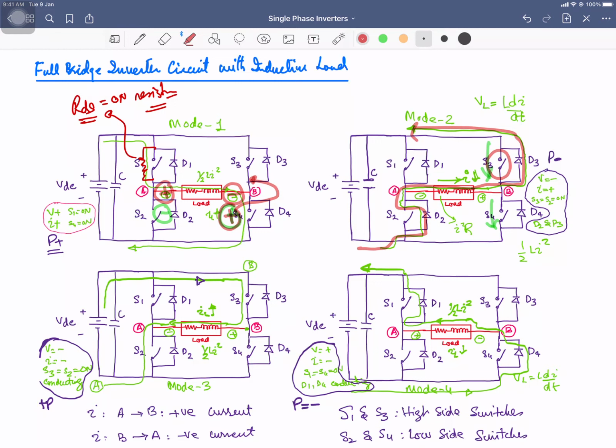So just like your diode, we have discussed it before, that your diode characteristics are like this. These are the forward characteristics, and in the reverse direction it is like that. Reverse breakdown voltage VBD, let's suppose, that is very high. The forward voltage is normally in the range of 0.7 volt for the silicon diode. So once you apply a very high negative voltage, there may occur the breakdown, the avalanche over here, and that can cause the failure of your diode.